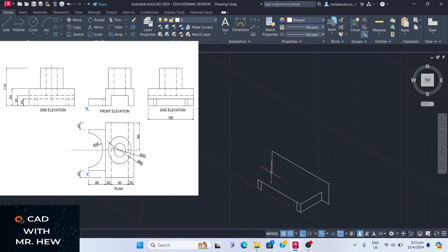What we're gonna do now, we're gonna draw a line from here going back 60 millimeters. So we go line from there, and the angle, I need to change this to the right if I want to go back that way, right? So this should be 60. Enter, right? Then coming back here now, we'd have to change this to the left so we can get this one. That is 120. Enter. All right, so are you seeing it now?